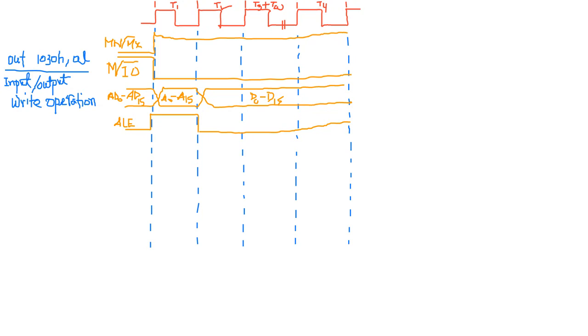And what about the data enable? To activate the data buffer, right? DEN, data enable, and it is with a bar. That means during the data time, it must be low. Must be low. Okay, so this is about that, and then what else?